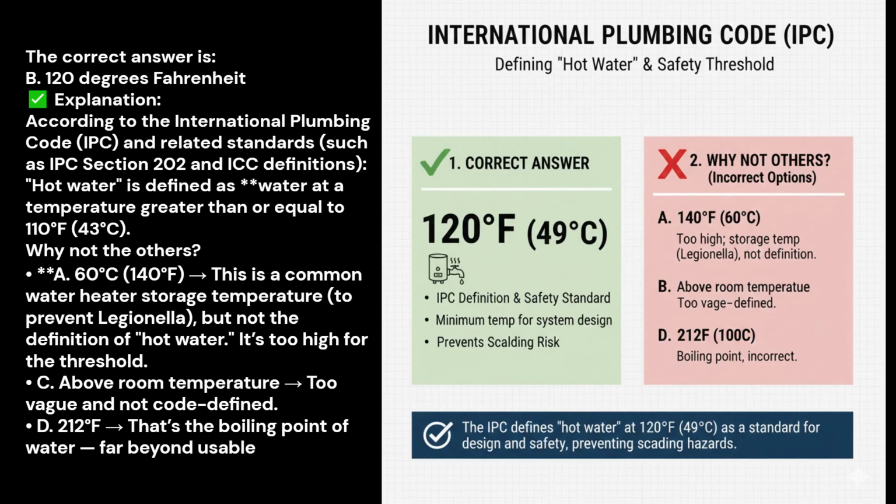Why the others are incorrect? B. That there is an excessive use of solvent cement, while possible. The instruction for many solvent weld joints specifically advises that a continuous bead should appear around the joint as proof of proper application and coverage. A small, uniform bead is the goal, not necessarily excessive. C. An improper jointing was made. The presence of the bead is generally a sign of a properly made joint.